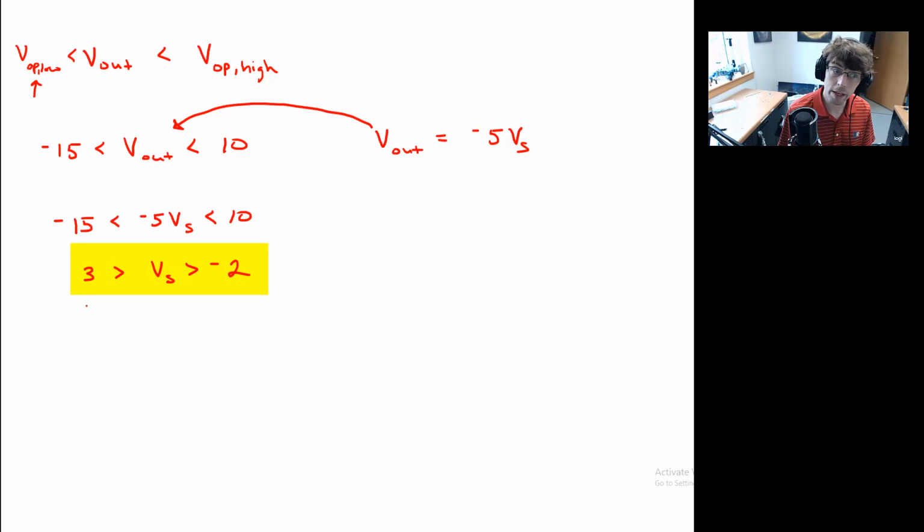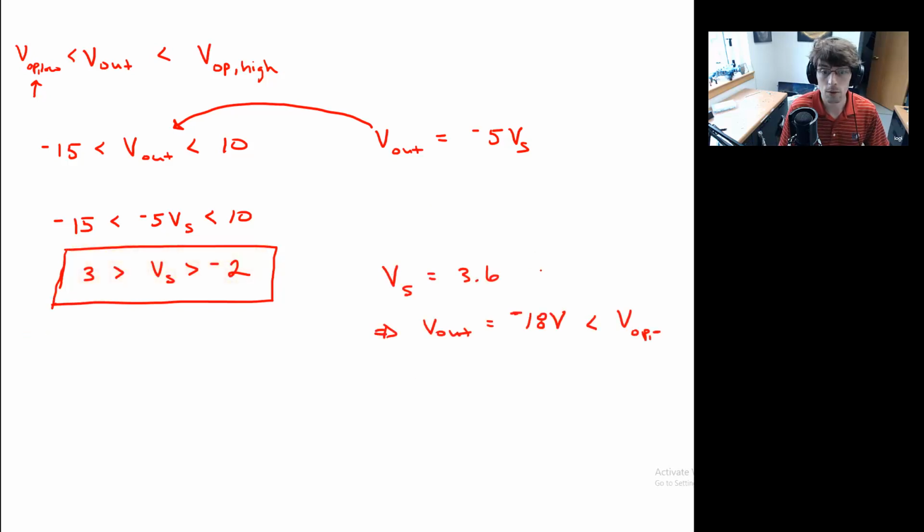And so right away, we see that we must have hit the saturation limit. So if we were actually to give it an input voltage of 3.6, rather than measuring 18 as the output voltage, we're actually going to get V out is equal to negative 15. Okay. C'est la vie. Can't do it. Cool, huh?